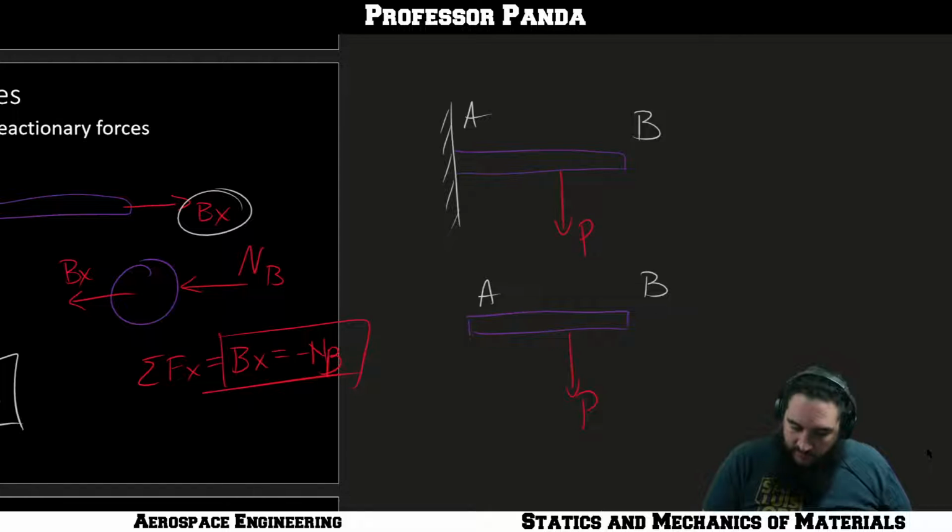the thing it's stuck into. Okay, and so if I have a rigidly attached beam, I'm going to get 3. I'm going to get an AX, I'm going to get an AY, and I'm going to get a moment. Okay, which way do I draw the moment?